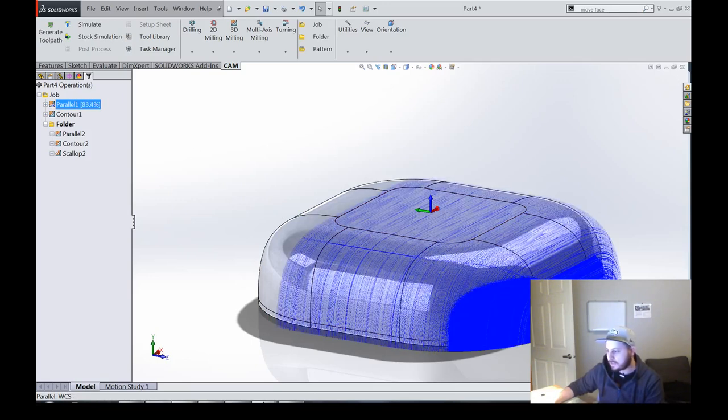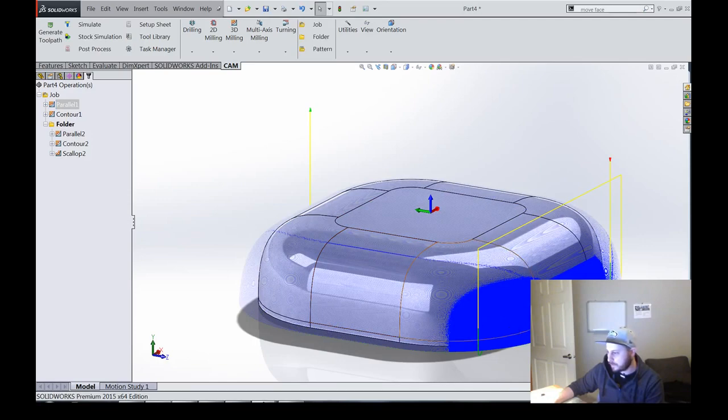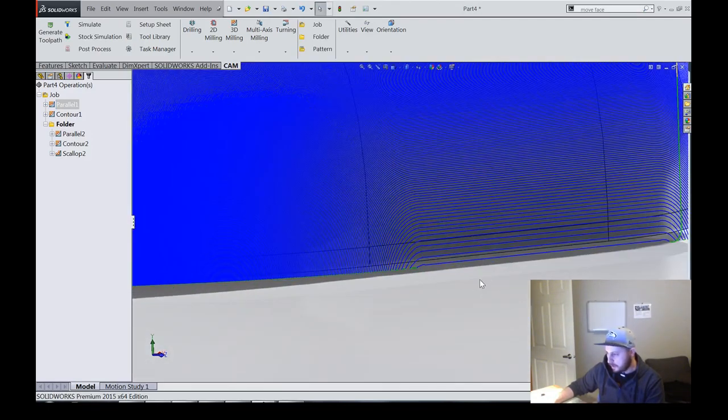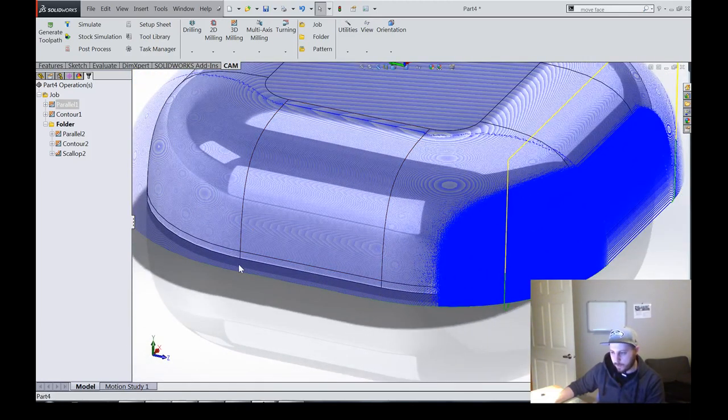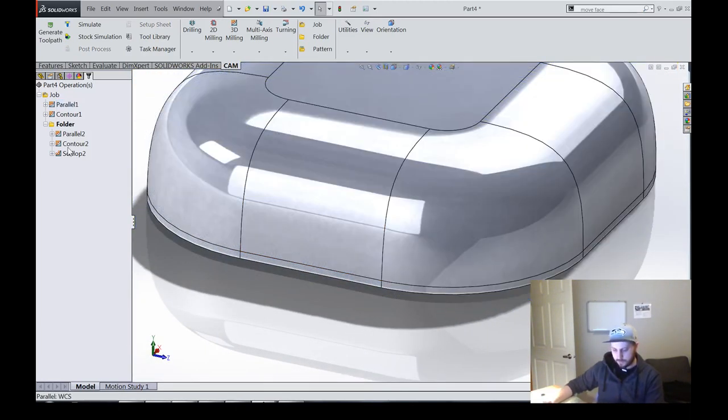It's going to take several times, literally 300 or 3,000 times, I don't know what that works out to be, longer, but now we have our minimum scallop over here. Obviously it is way, way tighter everywhere else. So efficiency basically boils down to having a constant scallop, or at least a near enough constant scallop that it's imperceptible and it really tightens up the efficiency there.